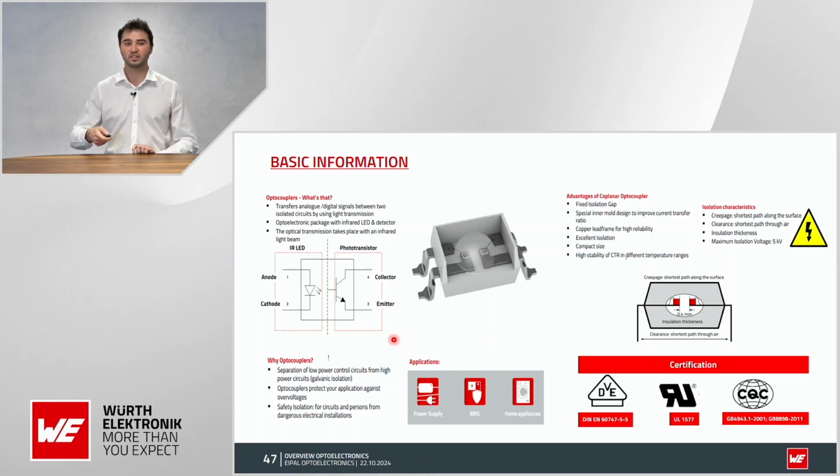But because the main application is to offer some insulation, we need to have certain certifications that we have for all of our optocouplers. So we have the VDE, UL, and CQC, mainly for the German and US market. Mainly the VDE and UL are the relevant ones, and we can have insulation of these components up to 5 kilovolts.